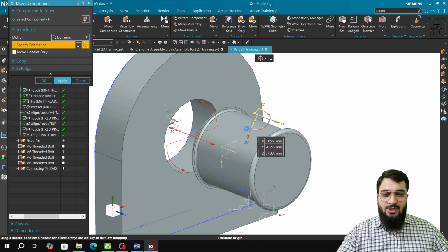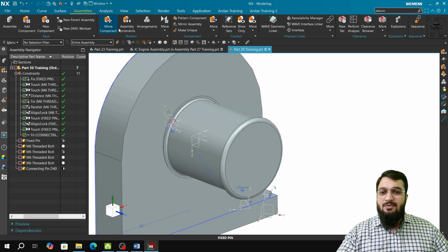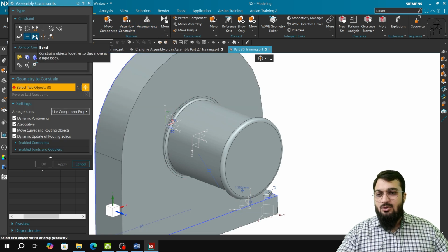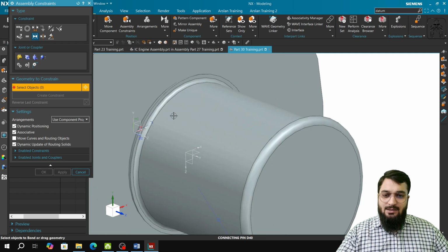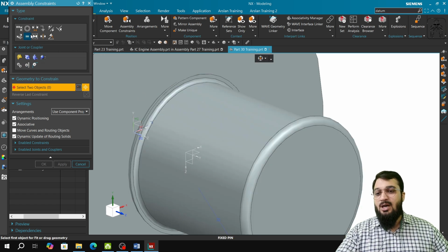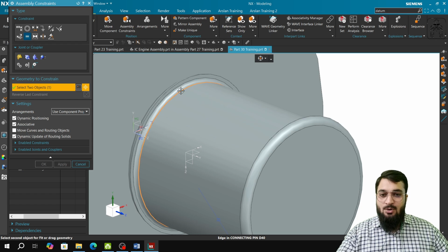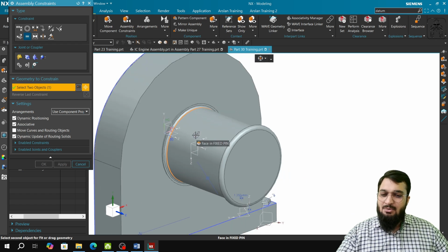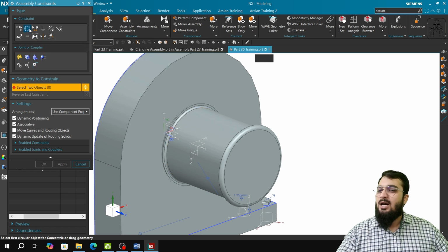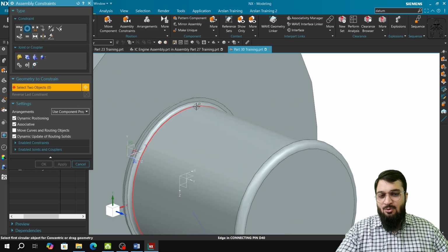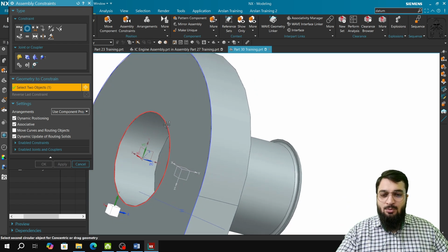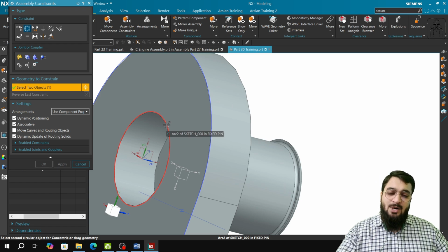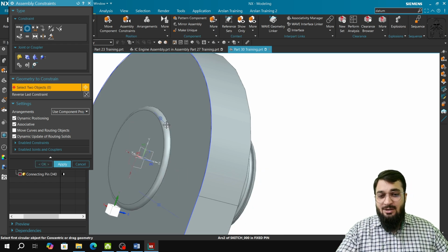After that, you can take the fit section and bond. Bond will allow you to keep this particular thing as it is. I'll again use the fit section, but that will not help, that will not solve the problem. I'll use the concentric constraint because I have no other option left. The concentric constraint allows two components having circular parts to get concentric, or get the same arc center with each other.